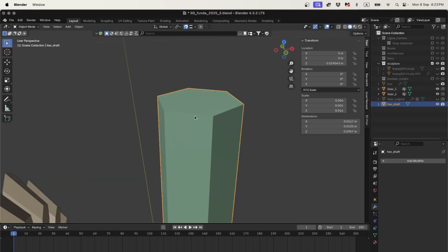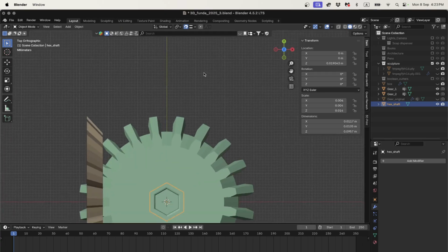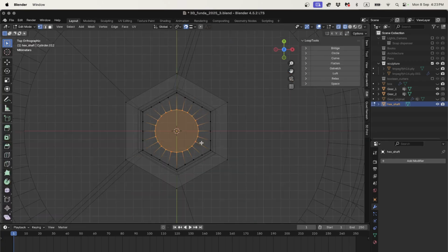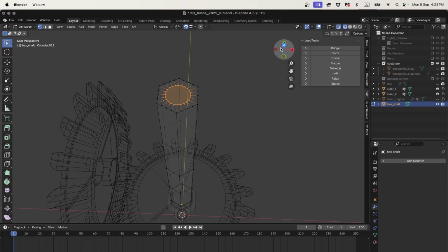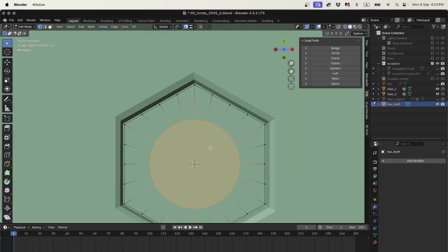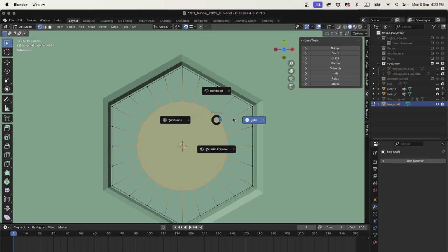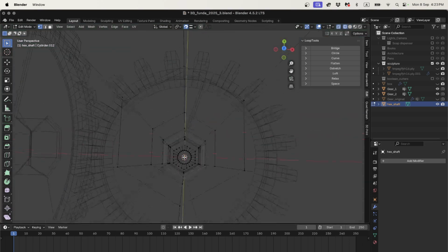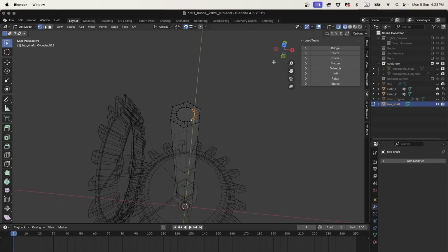So if we have a circular hole, that won't work, because with a round shape in a round hole, they can move, they won't be locked together. So that should be pretty easy for us to fix. I'm going to go into wireframe mode, and here I'm going to make sure I'm looking just at my top circle, that's good. And I'm going to select, in my solid view, shift select, I'm getting some vertexes. I'm going to get 7 vertexes here, and I'll just go into wireframe, check that I haven't got anything else by accident, okay?